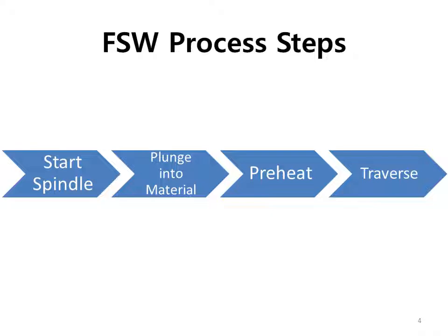After a short dwell time, the tool is moved forward along the joint line at the preset welding speed. Frictional heat is generated between the wear-resistant tool and the workpieces. This heat, along with that generated by the mechanical mixing process and the adiabatic heat within the material, causes the stirred materials to soften without melting. As the tool is moved forward, a special profile on the probe forces plasticised material from the leading face to the rear, where the forge forces assist in the consolidation of the weld.